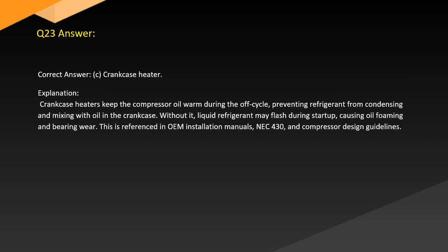Answer. Correct answer: C. Crankcase heater. Explanation. Crankcase heaters keep the compressor oil warm during the off cycle, preventing refrigerant from condensing and mixing with oil in the crankcase. Without it, liquid refrigerant may flash during startup, causing oil foaming and bearing wear. This is referenced in OEM installation manuals, NEC 430, and compressor design guidelines.